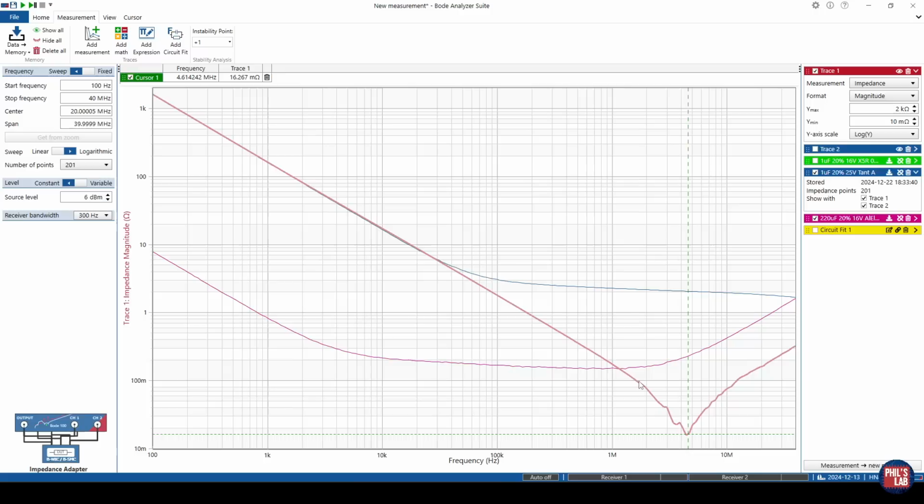If we just look at the multilayer ceramic capacitor, we can see there's a pretty defined resonance and overall a lower impedance from a specific higher frequency. So above about 1 megahertz, this multilayer ceramic capacitor up to about 20 megahertz or even higher has a far lower impedance than the tantalum as well as the electrolytic. However, we do have this pretty defined sharp resonance, plus the multilayer ceramic capacitor is sensitive to DC and AC bias derating, can have microphonic effects and more. It might be suitable for digital decoupling of a certain frequency range, but it might not be suitable for audio due to piezoelectric and microphonic effects.